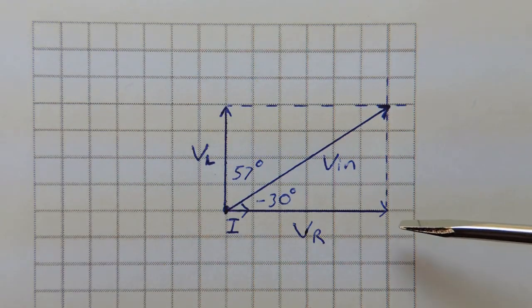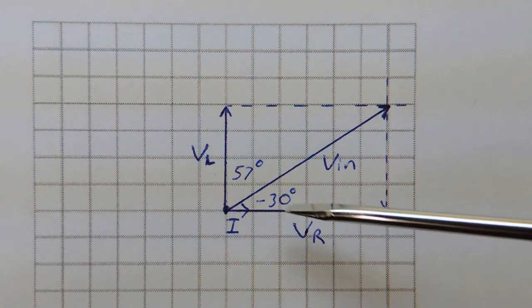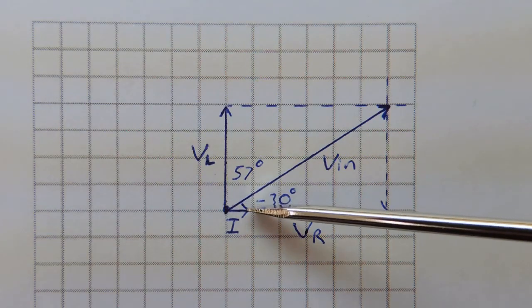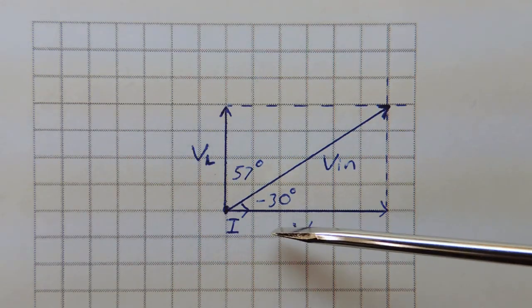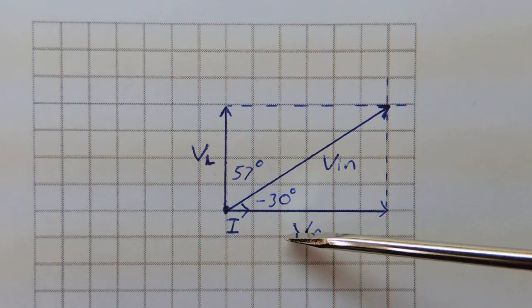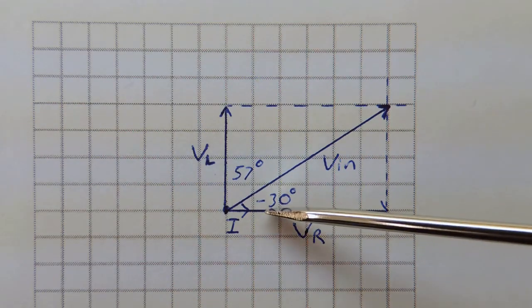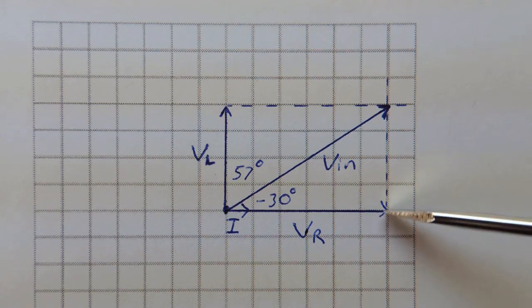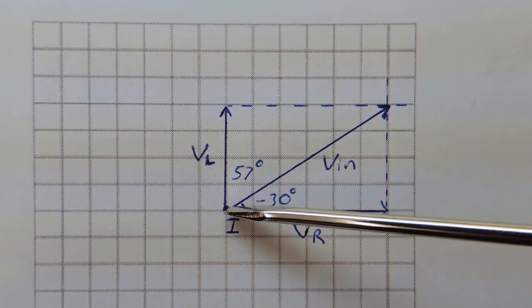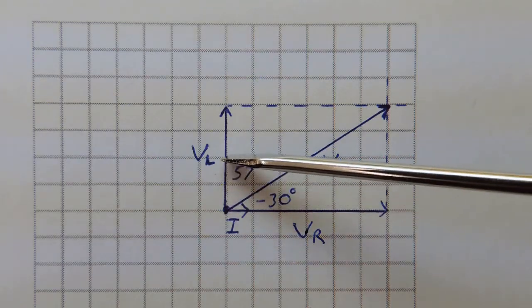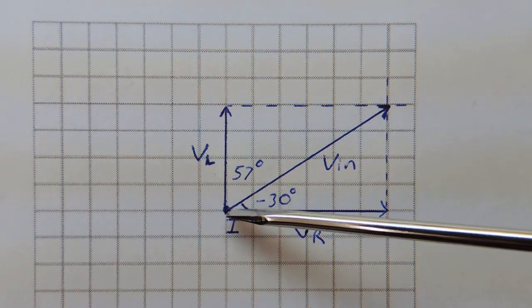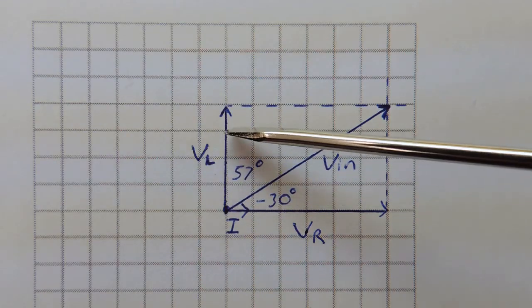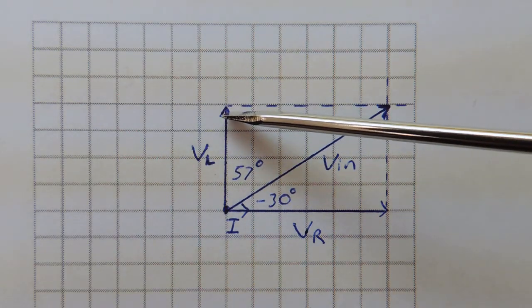So to draw the phasor diagram for plot 6.2, I start by putting I on the horizontal axes, and VR is in phase with I, and VR was 598 millivolts, so almost 1, 2, 3, 4, 5, almost 6 divisions. VL, remember VL is the plus J in the formula, so VL is up 90 degrees, and in this case VL was 378 millivolts, so 1, 2, 3, and not quite 4 divisions up.